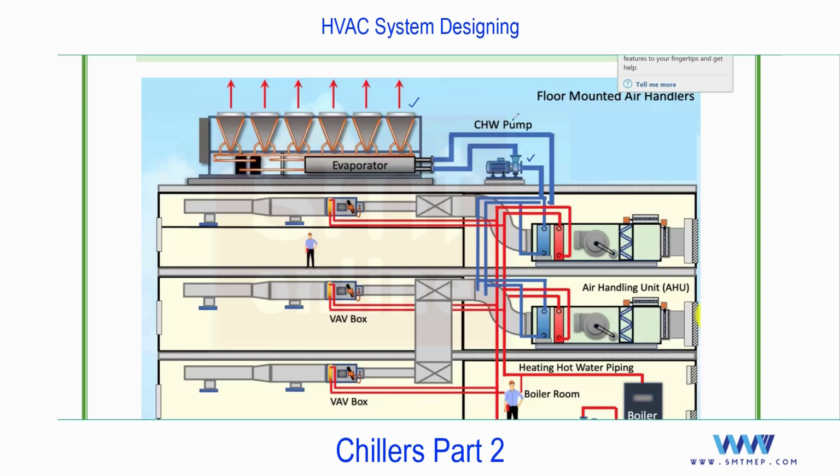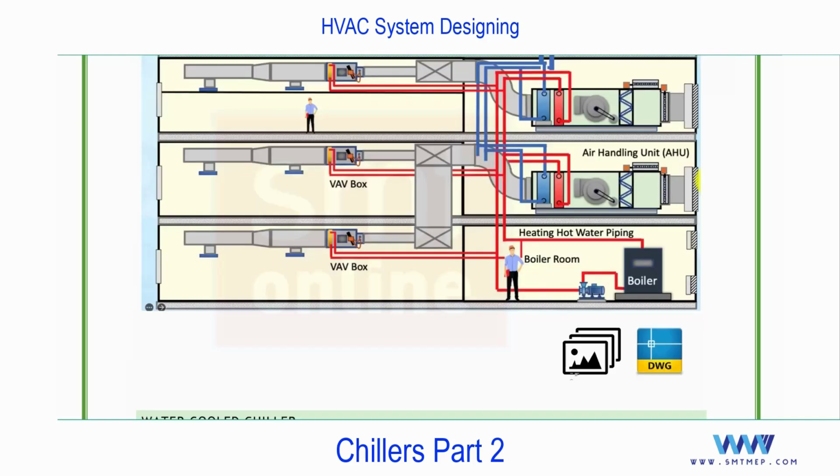So this is an air cooled chiller, and this you can consider as a chill water pump primary, and you can consider this is AHU1, AHU2. Forget about this boiler. In that you'll find the heating system also, that we'll discuss later. At this level just we're focusing on this chiller. So you see, from this chiller the chill water is going to circulate and supply in what? Cooling coil of evaporator. And this evaporator can be inside the AHU or can be inside this FCU to cool the air. Further with more details, let me open one drawing. With that you can try to understand the clear concept. But before this, let me show you some images.